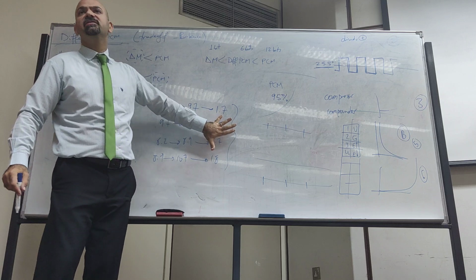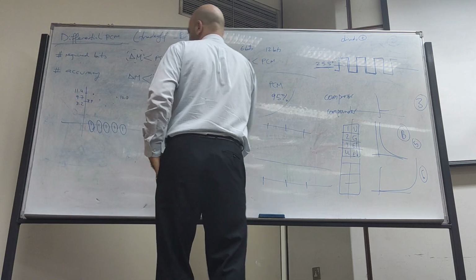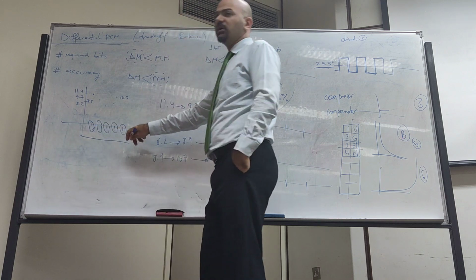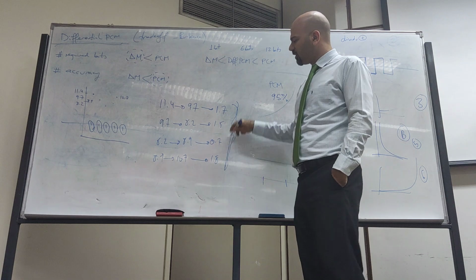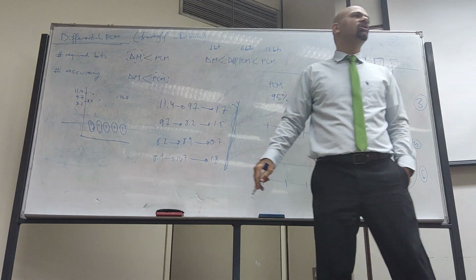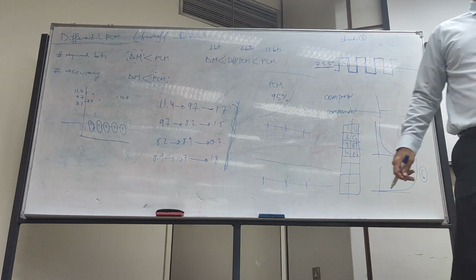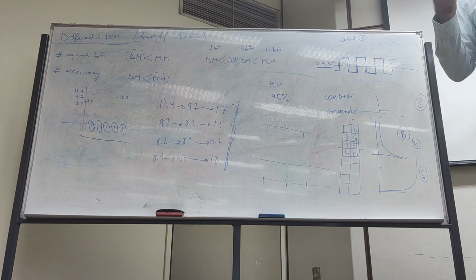The range is smaller. Whenever we deal with the original samples, the range is very large, so they can change a lot. But here, we are encoding smaller values, since the range between them is small. And what did we say today about the range? Increasing the range will reduce the SQNR, so whenever the range is smaller, our performance is better.